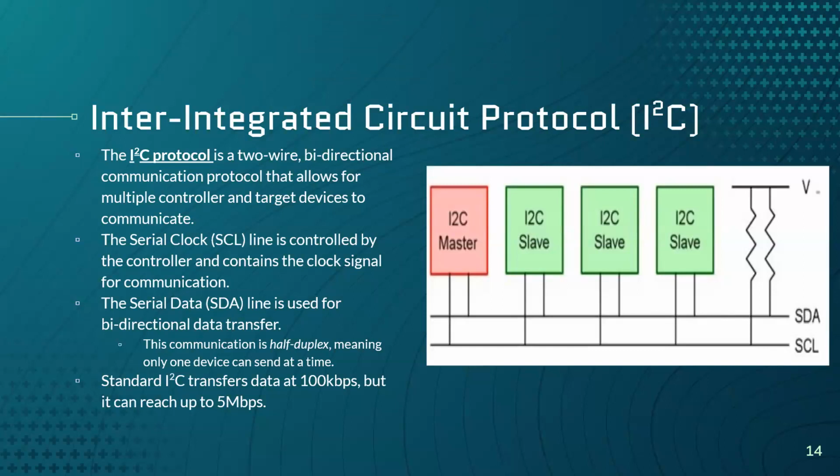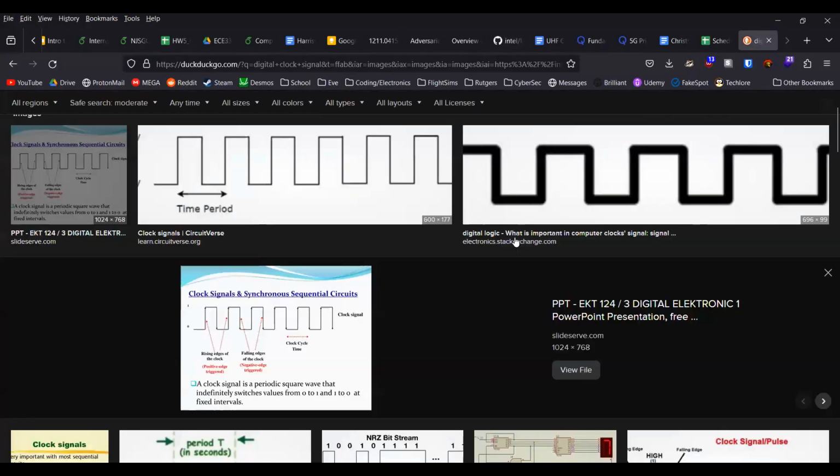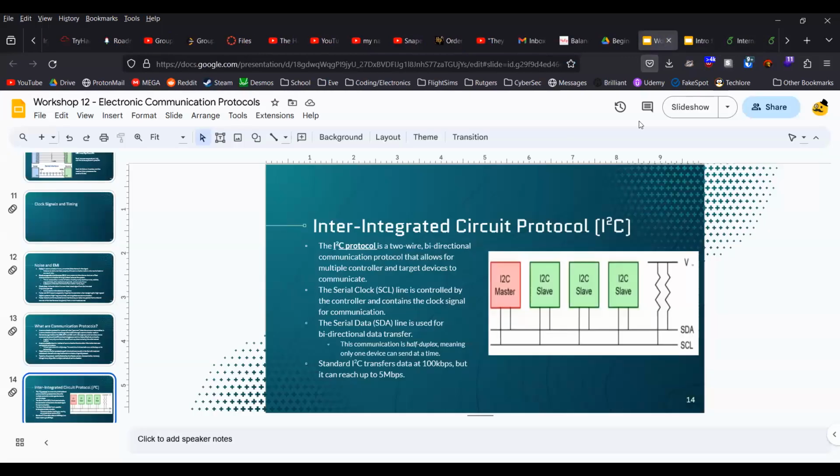Yeah, what's up? What this clock does and what kind of information it needs. So the clock in this case, on the actual clock line, it's just an up and down signal whose entire job is to synchronize when information is going to be sent. So it's just switching between 0 and 1 at fixed intervals. And the device will then use that switching signal because that signal is shared between the 2 devices or however many devices you're communicating with.